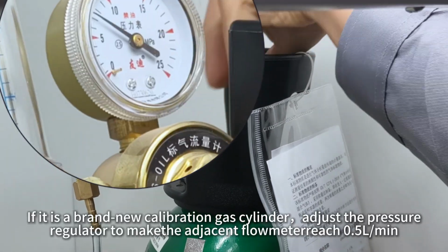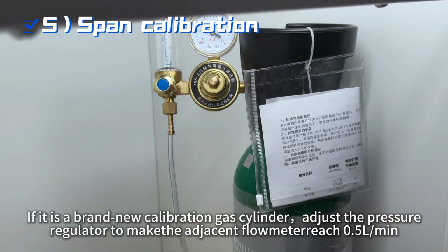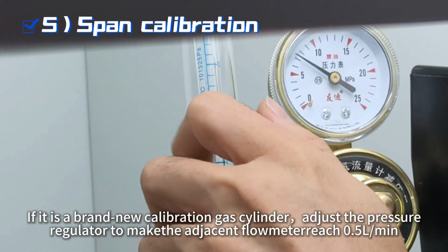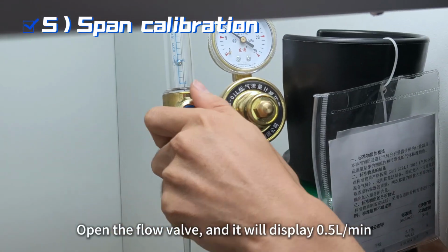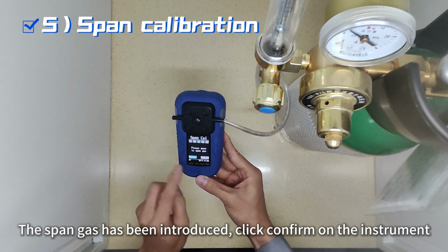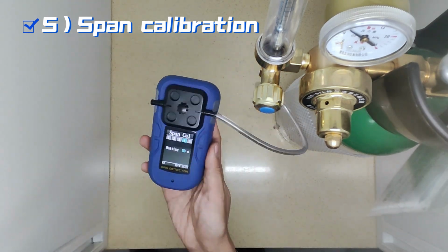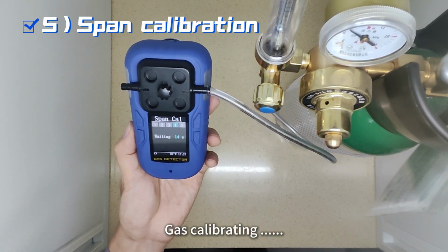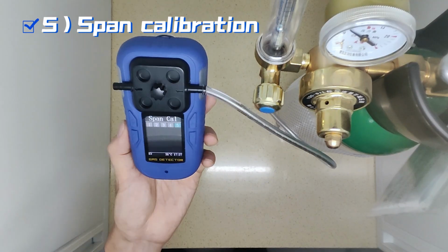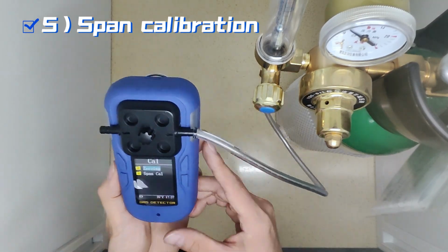If it is a brand new calibration gas cylinder, adjust the pressure regulator to make the adjacent flow meter reach 0.5 liters per minute. Open the flow valve, and it will display 0.5 liters per minute. The span gas has been introduced. Click Confirm on the instrument. It shows that all gases have been calibrated successfully.